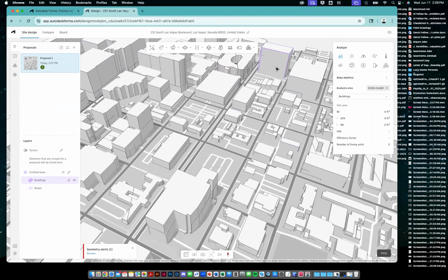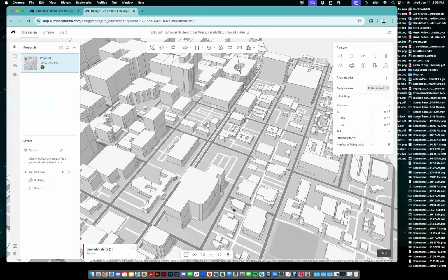And then if the massings are correct, it can also load in weather data, and then it uses computational fluid dynamics. You can do wind simulations. You can do wind roses. You can do solar analysis, looking at solar radiation averages over specific periods of time. So let's say in the winter versus the summer, or the day of the winter solstice versus the day of the summer solstice. And you can start to calculate FARs for the neighborhood, for a block, for a plot.